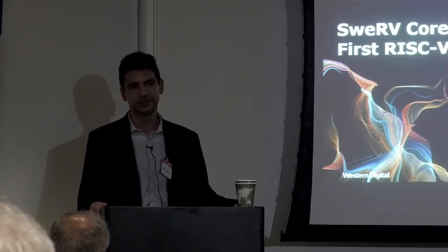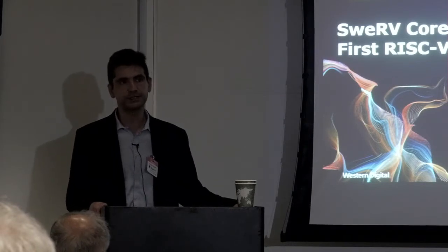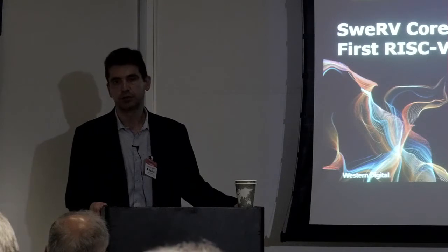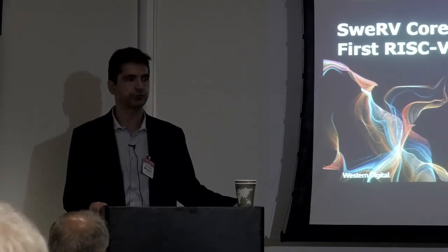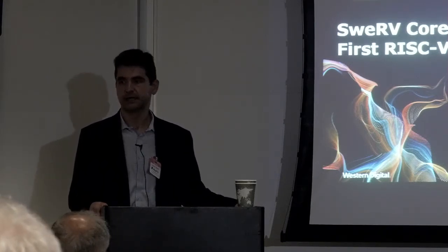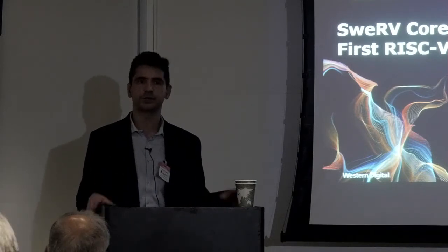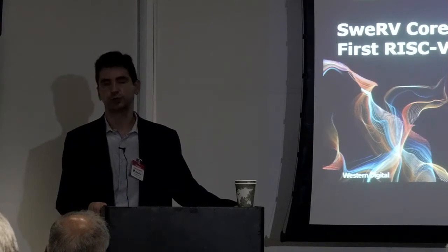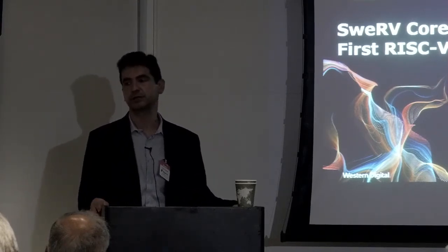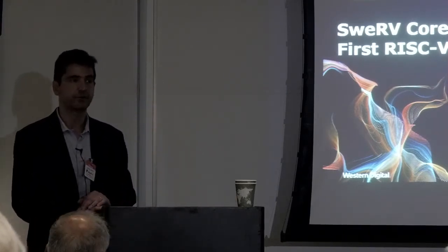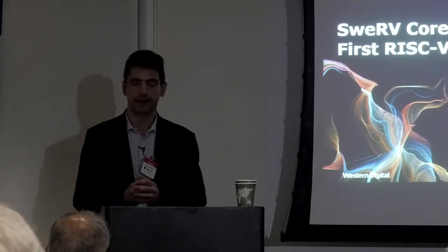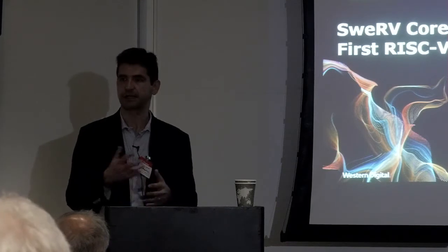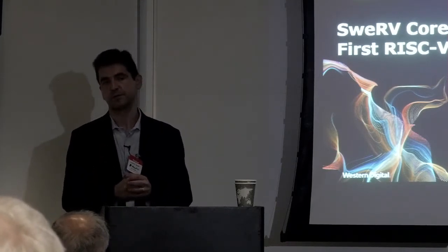But the general idea of the RISC computer is to have a small number of instructions, to simplify the formatting for instruction encoding, and to not try to implement too many complicated instructions that can, from a performance point of view, be done equivalently by using a few additional instructions, maybe sacrificing instruction bandwidth a little bit.